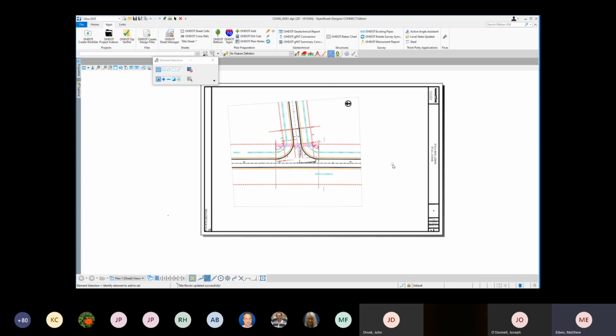The process is really the same as what we just did to create the second schematic sheet example, where we're going to create a seed file or create a new drawing using a design seed, and we're going to attach all our references to that design seed and place our name boundaries in there. As you saw on the previous slide, there are two options there where we can create all the plan sheets within one DGN file, and we'll just have a whole bunch of different models in there, or we can create one sheet per DGN file.